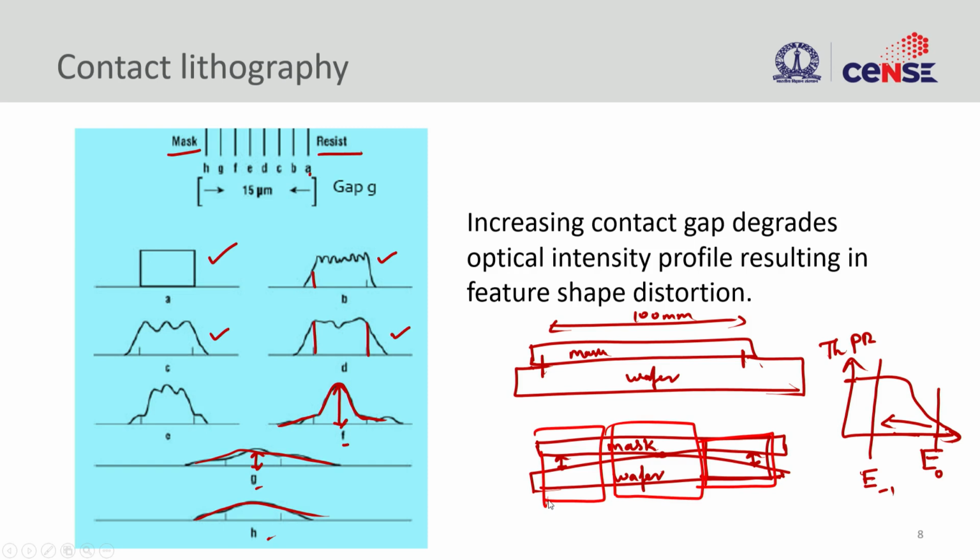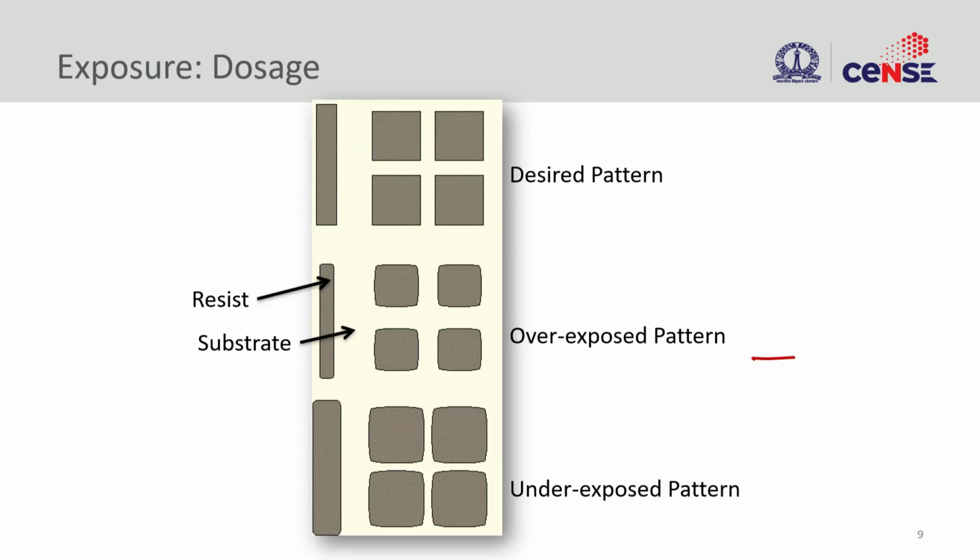So now if you take the wafer, whatever circuits you had at the center of the wafer will be desirable, but all the devices at the edges beyond the distance that we discussed are going to be out of spec, or some of the structures are not even illuminated at all. So this process will not yield what you are looking for. So it is very important to understand the flatness of the wafer and the flatness of the mask, so that you can later understand, if there is any failure, where it is coming from, and you can address those failures.